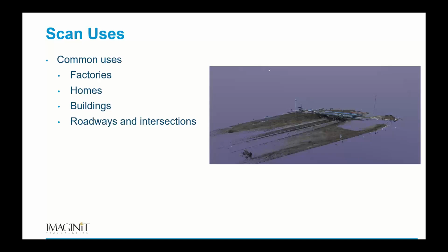All right. I'll tell you, this is not a survey grade scanner, but that doesn't mean that we can't use it in a survey environment. If I've got control, I can set my control up using the targets. We laser scan using the RTC. I'm able to go in, find those targets, find my control, register my point cloud to control. Now I'm set to that control. Now I'm within that survey grade tolerance.